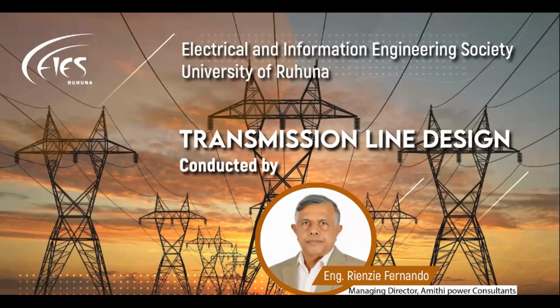Now, for a surge, when it's discharging, say 10 kiloamps is discharging through 10 ohms, you get about 100 kV, 10 ohms and 10 kA, so 100 kV potential rise at the tower foot, right?